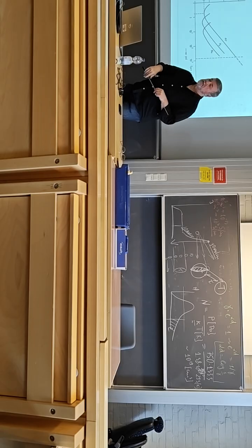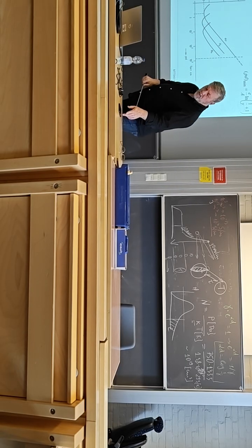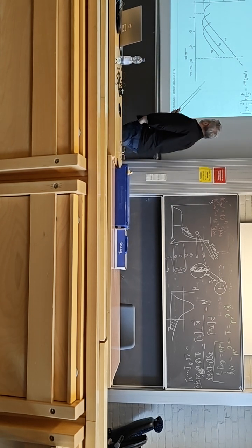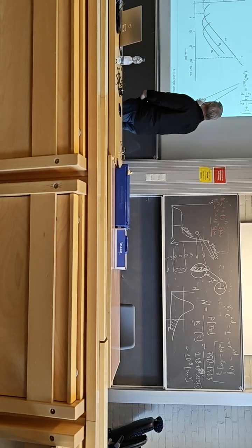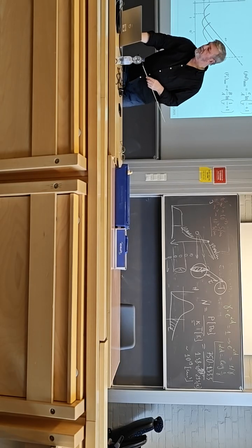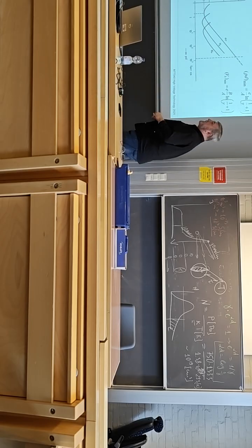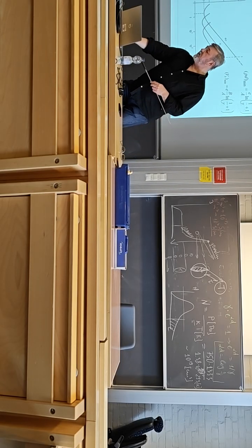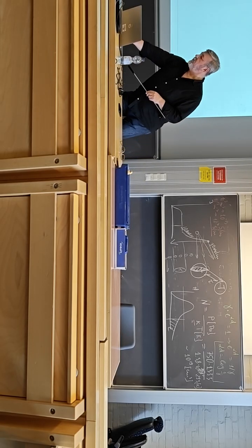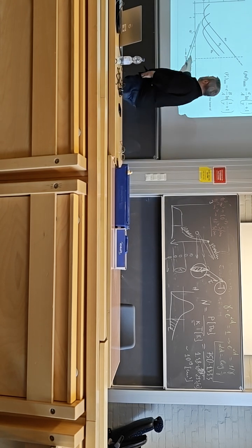So there is a minimum. What does this mean? Okay, 45, but I will finish with that, and then we take a break. So, one can take the derivative and try to find the pd which corresponds to the minimum here, and the respective minimum breakdown voltage. It's more or less a mathematical exercise based on the expression I showed before. But physically, what happens here? Why is there a minimum?